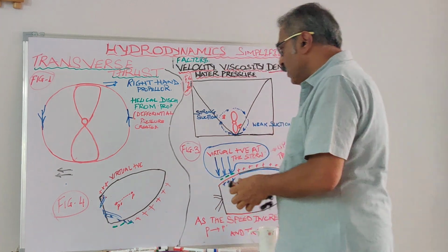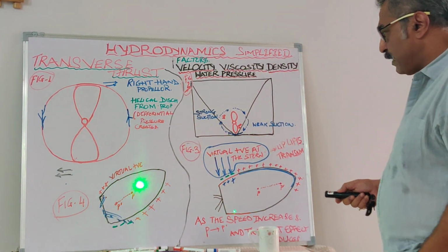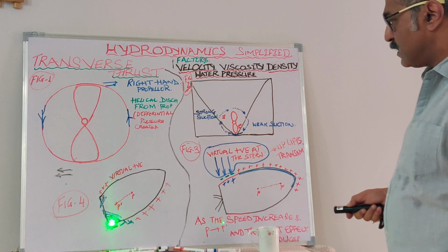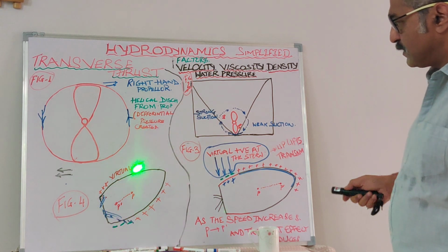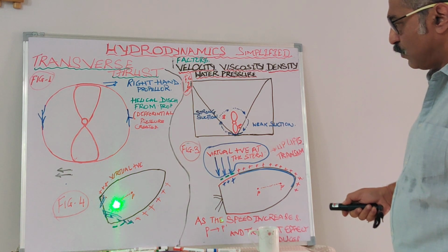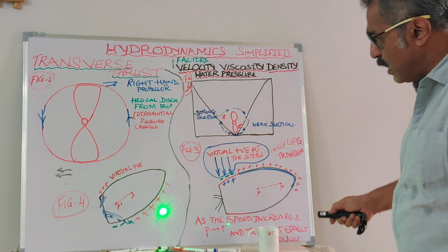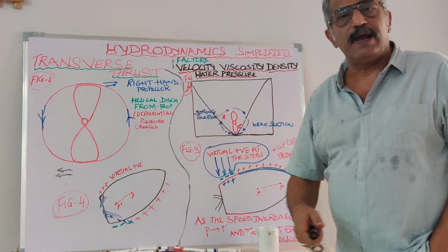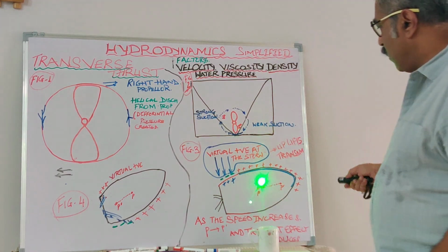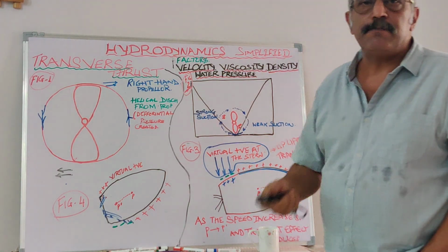Now, what is happening when the vessel is going on the stern thrust? The water is going forward, the vessel is drawing aft, and the pivot point is coming to 1/4 of the length from the stern. At the same time, the underwater volume of the displacement, again, what I explained earlier, plays a major role.